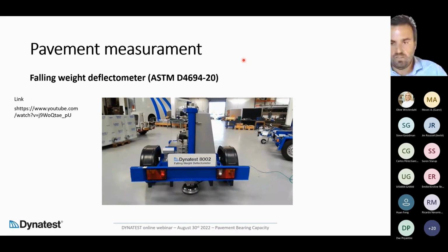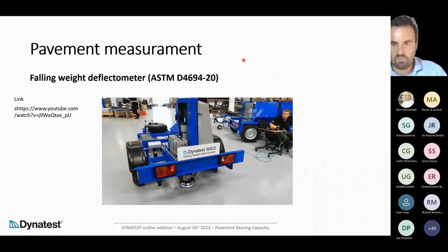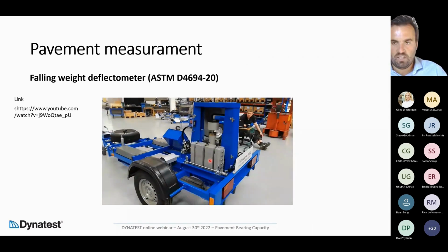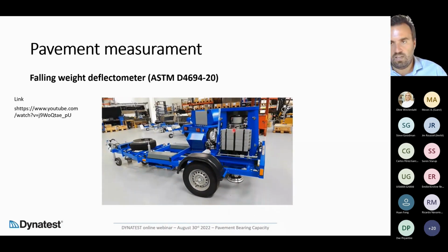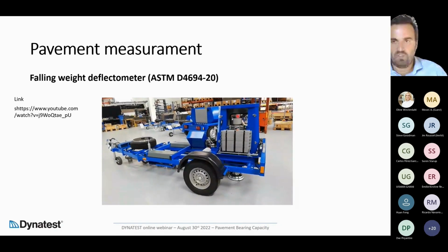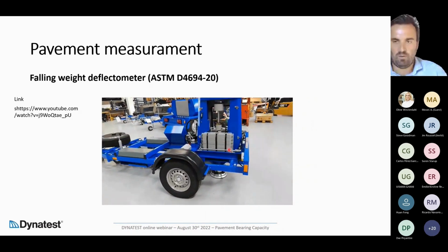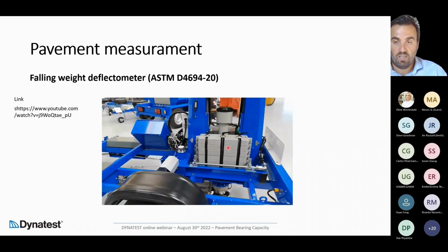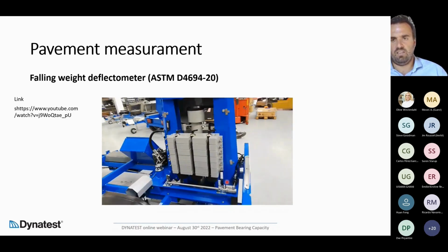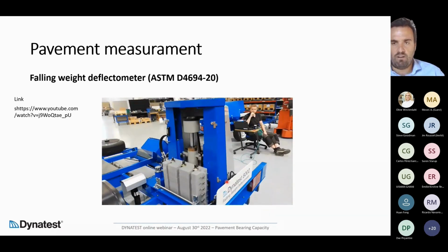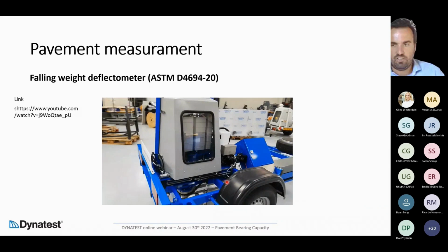This is a video about the falling weight test. So the loading plate is placed down, and the geophones that are here. One mass is raised. The number of masses can be changed, and also the height of drop can be changed. So in the moment where the mass is released, the deflection is recorded. Usually it takes around 1 minute to arrive at one station place, run 3 drops, raise the plate and the geophones, and move away.